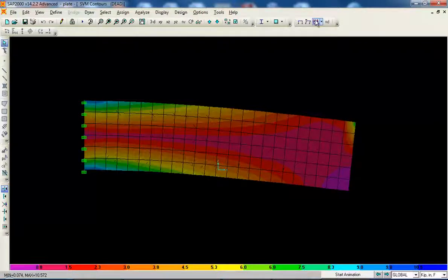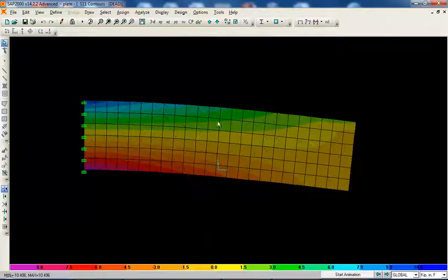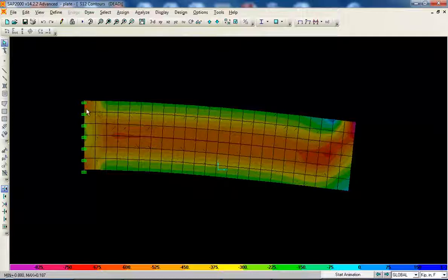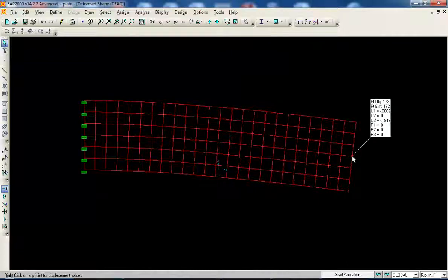So for your homework, I would mostly like you to compare the normal stress around those locations with your other calculations, and then also the shear stress. For shear stress, don't go there because there's a whole bunch of stress concentrations. Just go to the ending place here. Just do a maximum here or something, and then I want you to compare the deflection at the tip. That's it for this one.